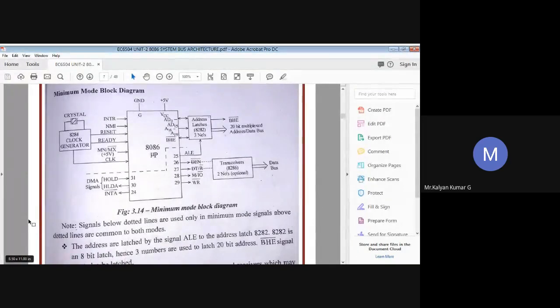I'll just recollect what pins are available. We'll have a clock synchronization pin, a peripheral clock pin, address enables AEN1, AEN2, ready 1, ready 2, bus ready. We'll have the clock signal, ground, VCC, and two pins, X1 and X2, for crystal connection. And we have EFI, the external frequency input option, OSC, the oscillator output, and then reset and RES bar.